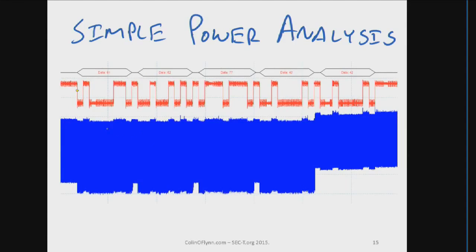So this is another, I don't have it here, but this was a bootloader that had password protection on it. If you sent the wrong password, it simply never responded. It just spun into a loop and you had to power cycle the device. The problem was, because it was a very small bootloader, they tried to make it as small as possible, so as soon as it detected the wrong digit in a password, it spun into that infinite loop.